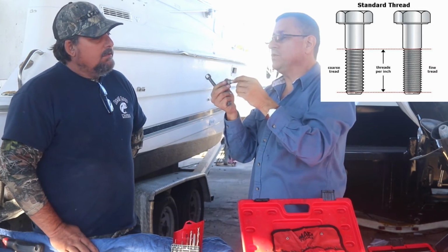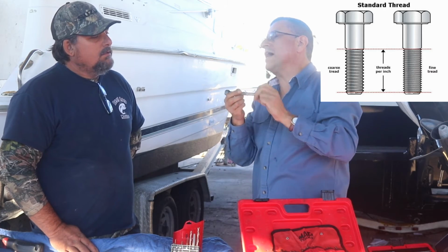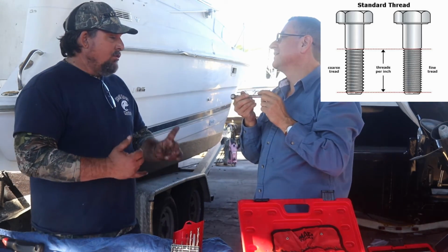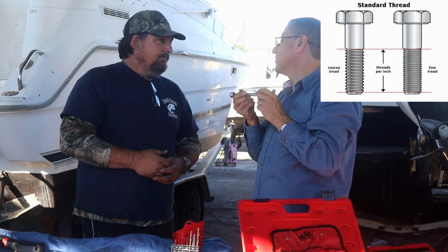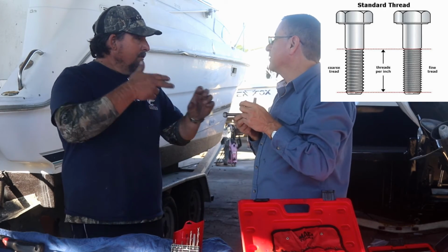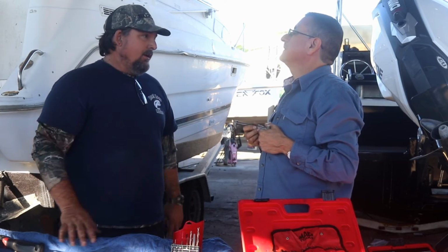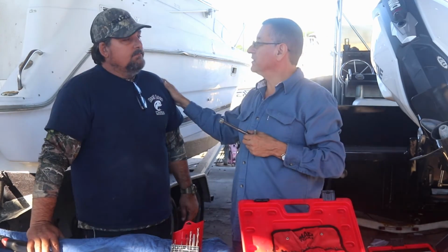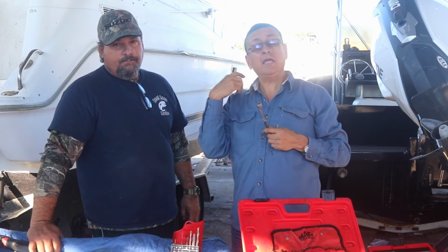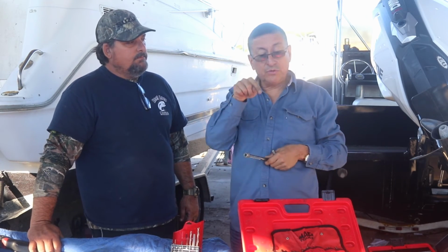And what happens when you try to introduce a fine bolt into a coarse thread? Well, you damage the threads on the bolt, and you can damage the nut. Correct. Or if you're putting it in the engine, you can damage the engine. And then you're going to have to use a tool to repair the threads. Yes, and this is one of the laboratories that we are going to do. We are going to explain in the laboratory the procedure to repair threads. We are going to use the taps and the dies.